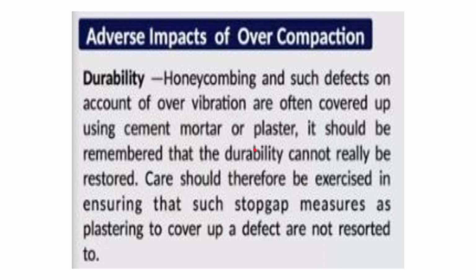Apart from that, there is even the issue of durability. Okay, honeycombing and such defects on account of over vibration are often covered up using cement mortar or plaster. Okay, so this is a very simple solution, but it is not a long lasting one. It should be remembered that the durability cannot really be restored if honeycombing and such defects are present. So care should be exercised to ensure that such stopgap measures as plastering to cover up the defects are not resorted to.